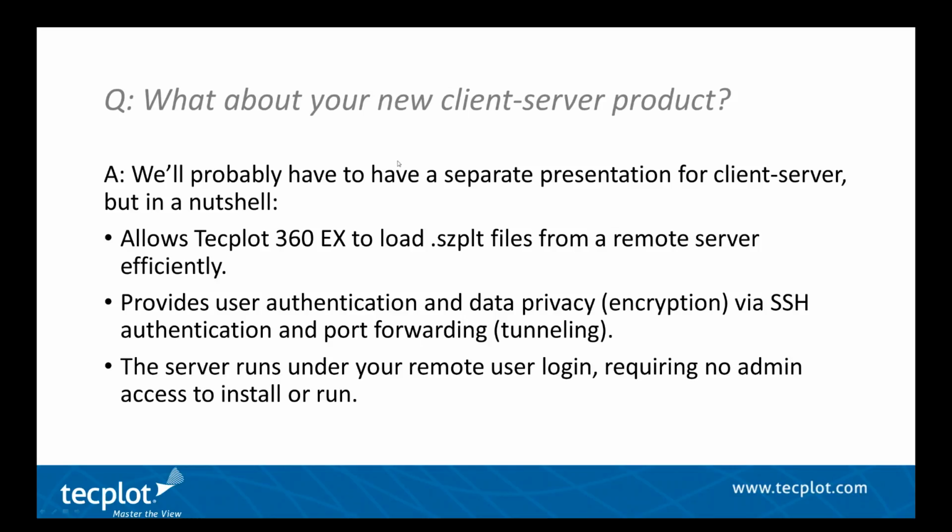Yeah, and by the way, going the other way from PLT, or for that matter, pretty much any format that Tecplot supports, that Tecplot will read, you can do the same sort of thing where you can read it into Tecplot and write it out as SCPLT files. And you can do it in batch with the -convert flag. And it'll be just like a command line converter. If you do that, it does not check out a license.